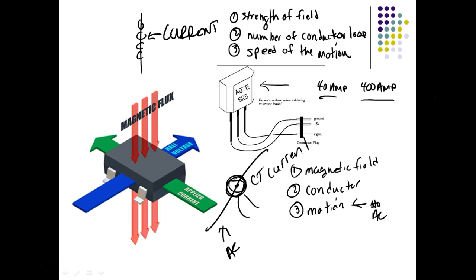So these guys are really good for measuring what? High current, like motors. You see a lot of electricians wire them. Now there is a trick you can use. You can take the clamp and then you can loop the wire. If you loop the wire twice, then your meter is going to measure twice what it's supposed to do. So you can make it measure smaller currents, right?